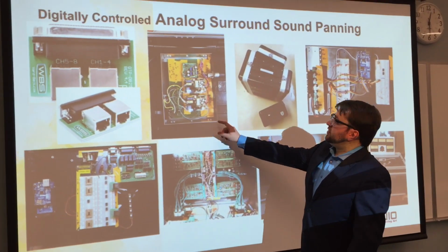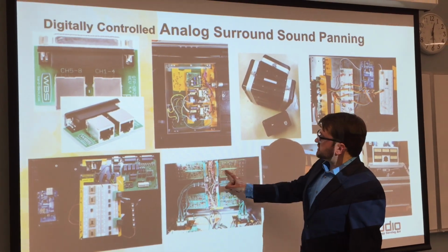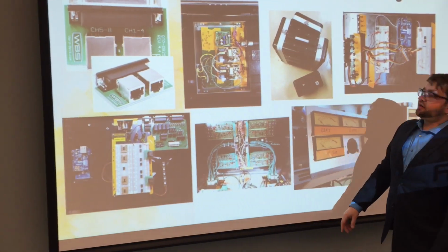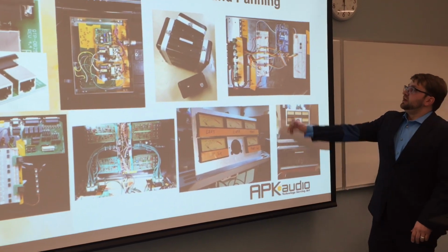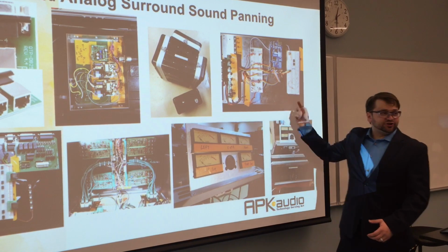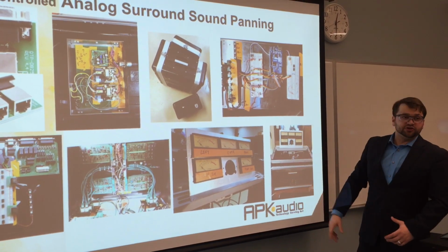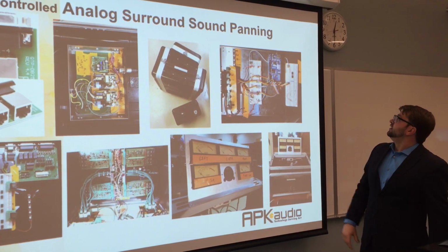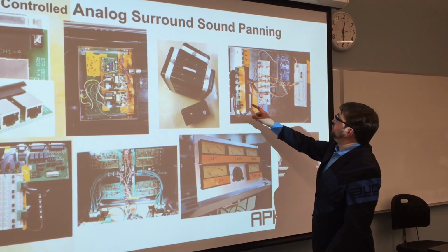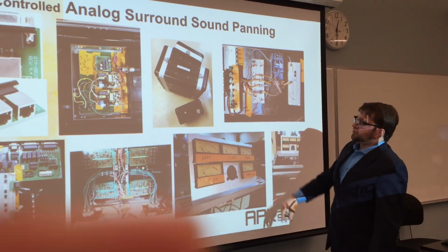Power supply, I needed plus minus 24 volts to run the summing amp, plus minus 7 volts to run the audio side of the controlled potentiometers. The beauty of working in a factory: you need a rack-mounted tray, just go to the garbage and they got rack-mounted trays everywhere and you just stick it on and away you go. All of their buttons were repurposed and then wired to the Mega and so on and so forth.